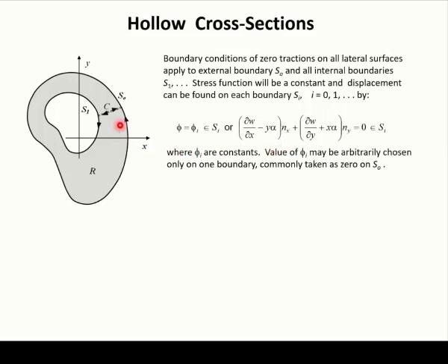Since the stress functions inside are constants, we can select any constant value. And again, don't forget that generally we take the stress function as 0 on the outer surface, but on the inner surface we can select any constant value.